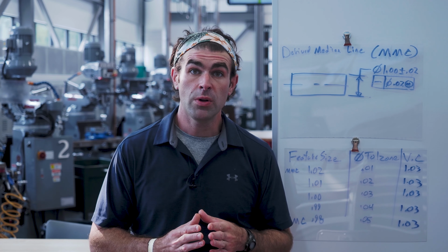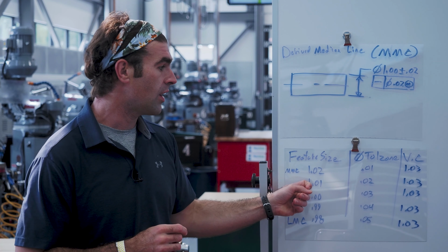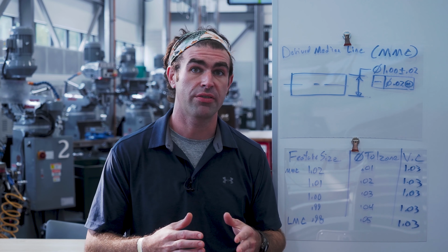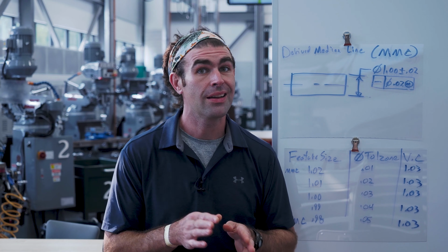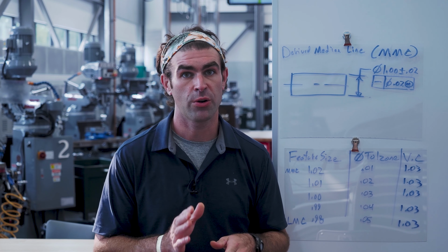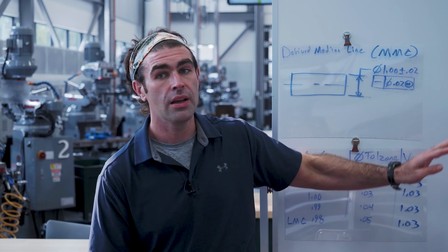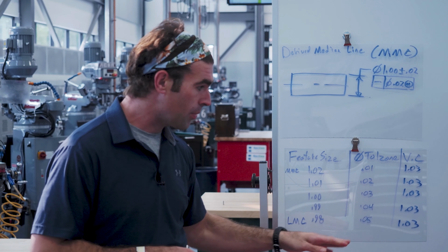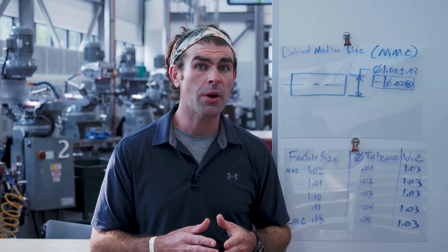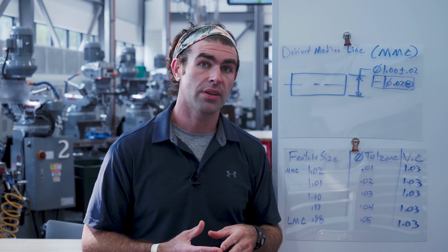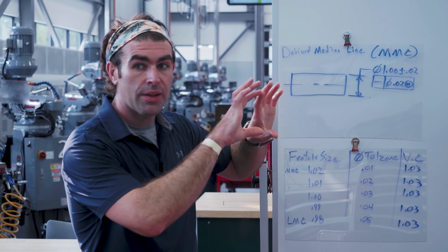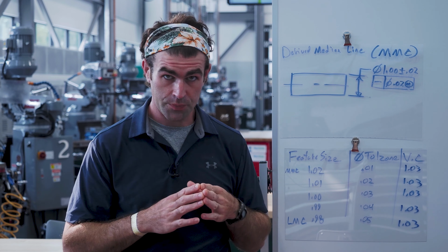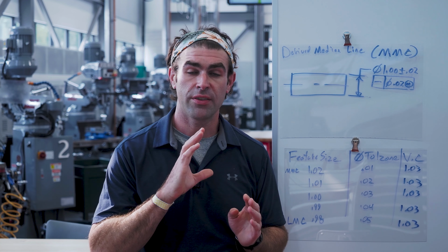The next term we'll deal with: if you add the feature size and the tolerance zone, the tolerance you have on that feature, you get what's called a virtual condition. Now this only applies when you're using MMC. If you're using regardless of feature size, so nothing here, it's called the outer boundary. But if you notice, if we add these two numbers up, it's always the same. This is where hard gauging comes in. So what happens is the part gets smaller, it's allowed to bend more or have any kind of irregularities. But the idea is it'll always fit in the same size place, right?